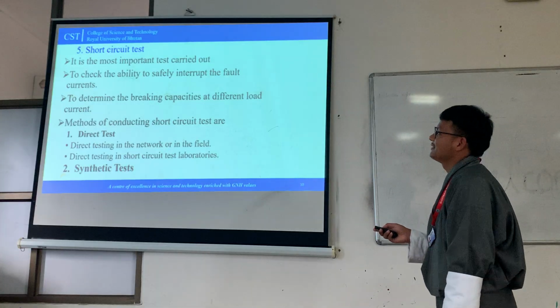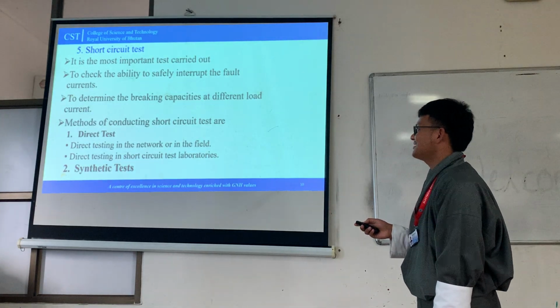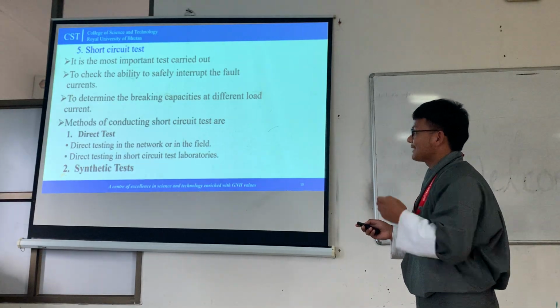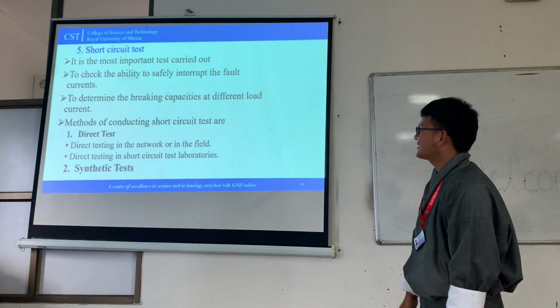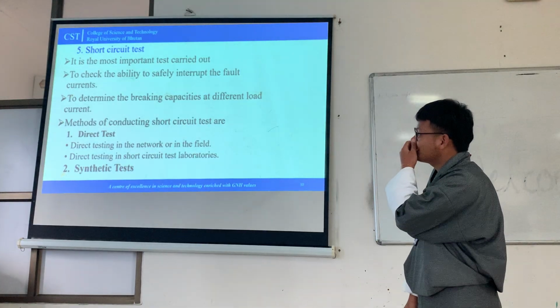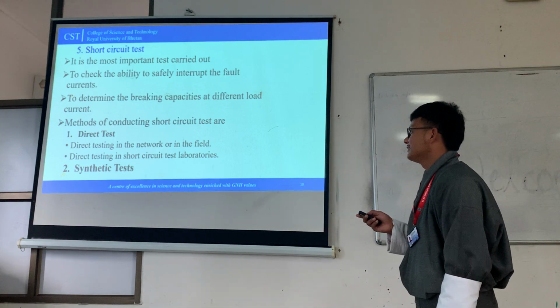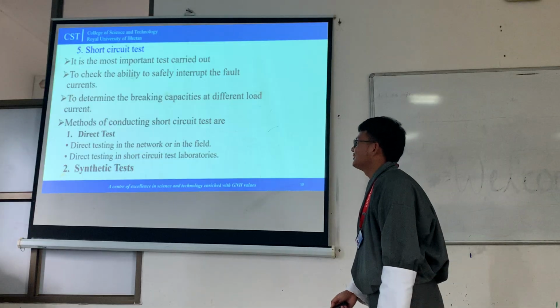Number 6 is the short circuit test. The main purpose of doing the short circuit test is to see that the breaker can break a high current, and it's the most important test. It's detected and the breaking capacity is determined at the end of the test.